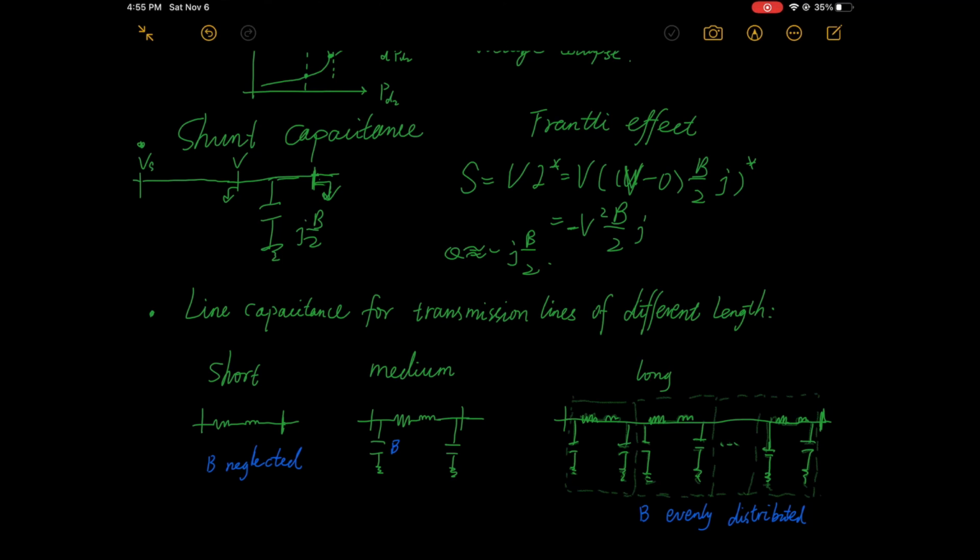Another thing to notice is that although we often mention QV coupling and PF coupling, it doesn't mean that P and V or Q and F are isolated. We do find that low active power loads lead to a voltage boost due to line capacitance. It is just in steady-state analysis near a stable frequency that we can use phasor expression, and then we can do PF or QV control separately.